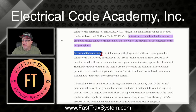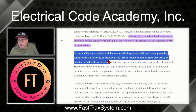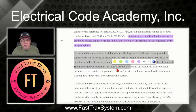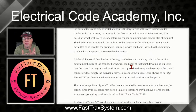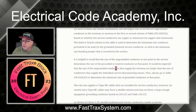So for each of these similar installations, the use of the largest size of the service ungrounded conductor in the wireway or raceway, in the first or second column we looked at, was what told you the copper or aluminum columns. And then, of course, the sizing of the grounded conductor is in column 3 and column 4, based on whether it's copper or aluminum. Now, it is helpful to recall that the size of the ungrounded conductor at this point is the driving factor for sizing that neutral, the minimum size. It's the driving point. That's why we took those ungrounded conductors and used them with that table to size it. So it's important to remember that when you're doing that.